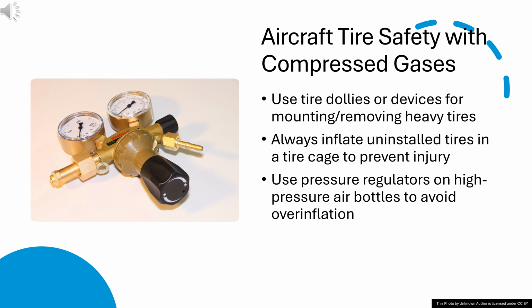Servicing aircraft tires with compressed gases requires extreme caution. Always use tire dollies to manage heavy tires and inflate uninstalled tires within a tire cage to protect against overinflation injuries. High-pressure air systems must have regulators.